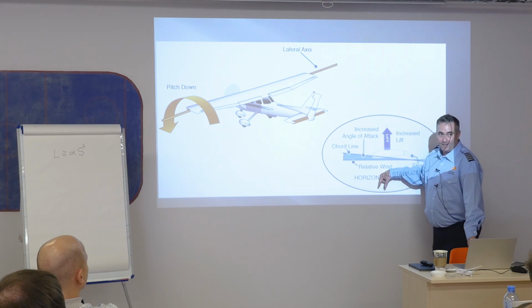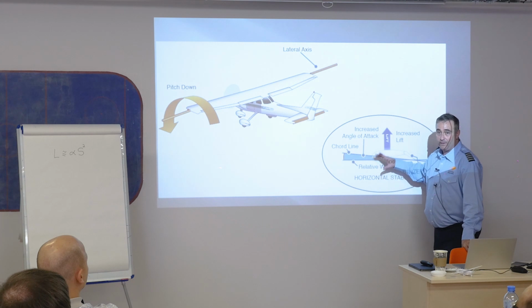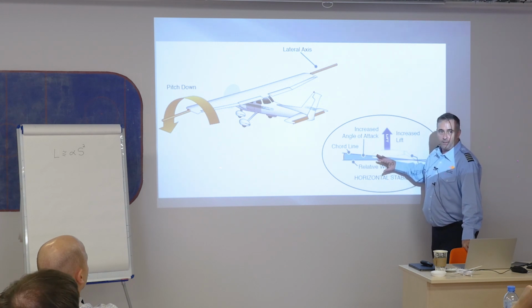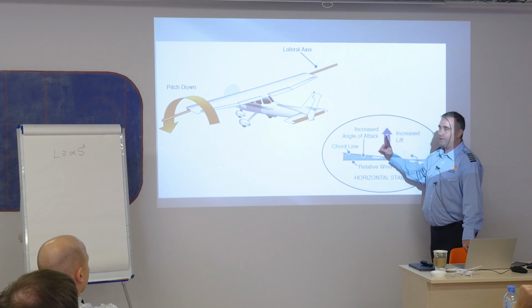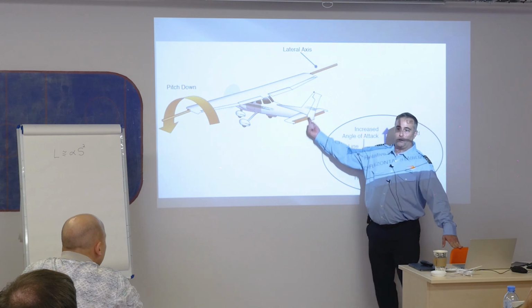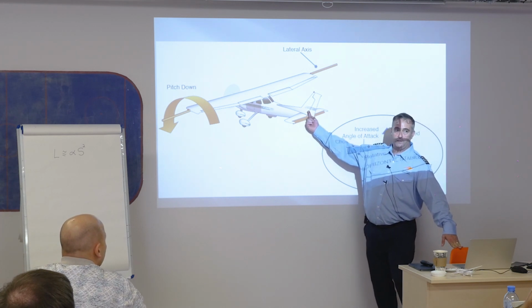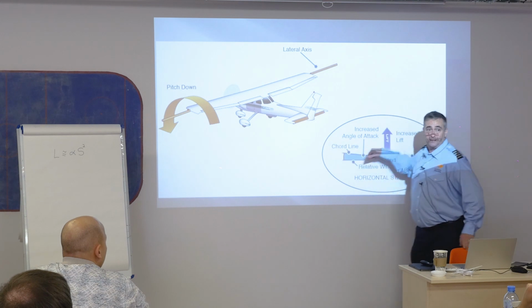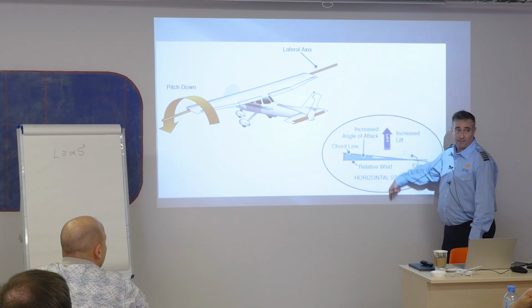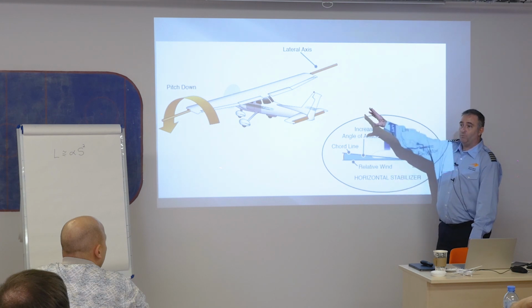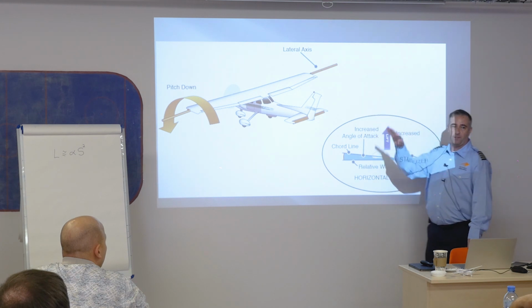I hope so. I know the charging thing or whatever, but here, for us to understand any of the stability, it's very, very important that you don't get this confused with the tail force making lift going upwards. Okay? Because it does not. The tail force is causing lift in a downward motion. If it didn't, this airplane would not behave in a manner that's predictable.